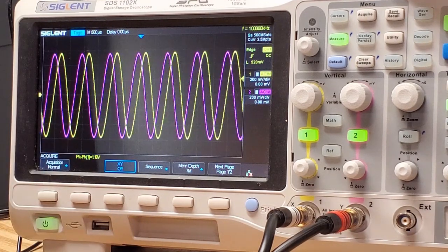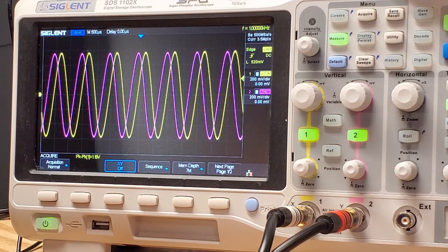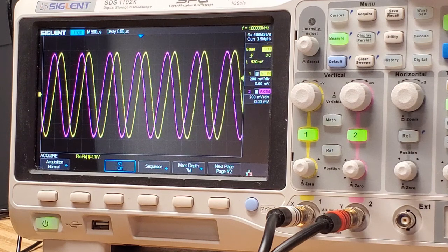So let's move now to one of the things that you'll find, which is that this is processed with 101 taps. So there's a certain limit to the amount of processing that you can do on the ESP32. And so let's see what happens when you cross that limit. So what I'll do is I'll change the code to run instead with 251 taps.